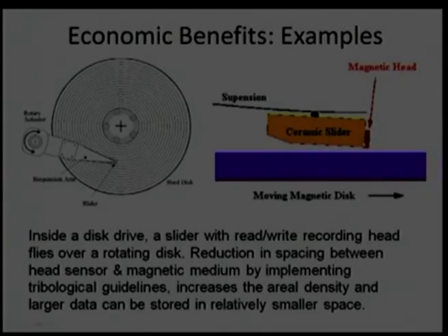When the magnetic head is available here, if the gap between head and disk is very narrow, a very low value, then there is a possibility of boundary lubrication, there is a possibility that the surface roughness of the magnetic disk may hurt the head and damage the head. There is a possibility. However, if we design this properly, then that possibility can be reduced.